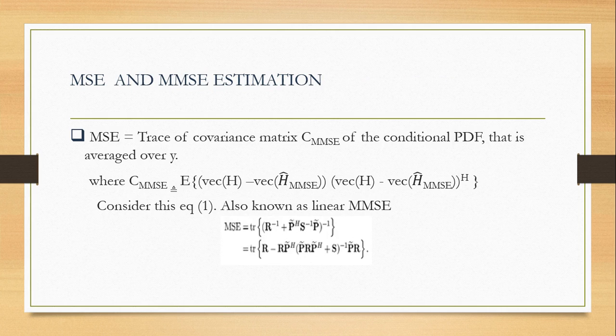The most important thing to note while determining MSE is that MSE is entirely dependent on the training matrix P. Therefore, optimization of the training matrix is very important to get a healthy MSE. There are a lot of heuristics that are being proposed, and these heuristics are based on the total power. The total power is determined, and the shortest training sequence length for the smallest MSE is also determined.